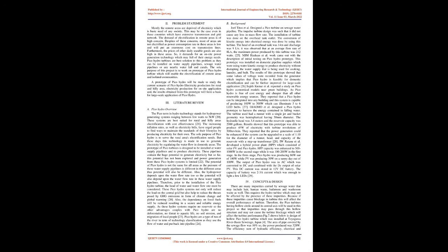Furthermore, the turbine consists of 3 more major components, which are termed the scroll case, draft tube, and wicket gates. Further classification of propeller turbines goes into bulb turbine, with the generator installed in front of the water flow; Straflo, with the generator directly attached to the turbine circumference; and tube turbine, where the penstock and generator connection is a straight line.